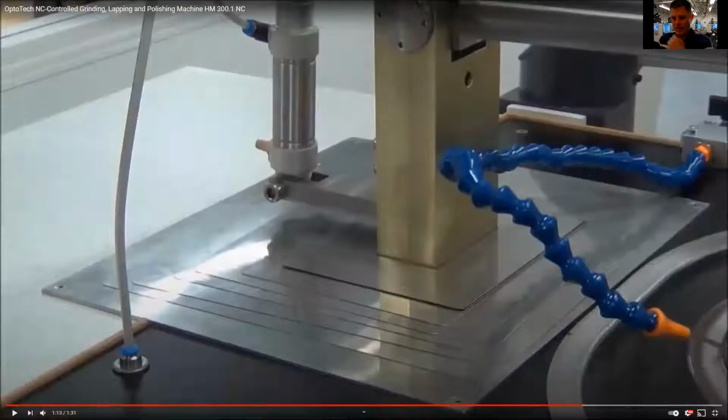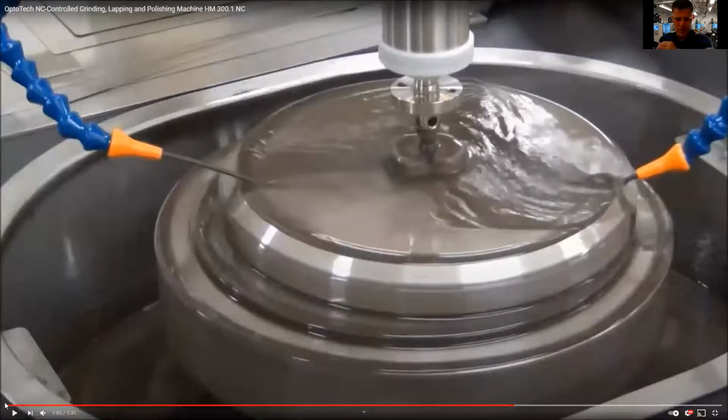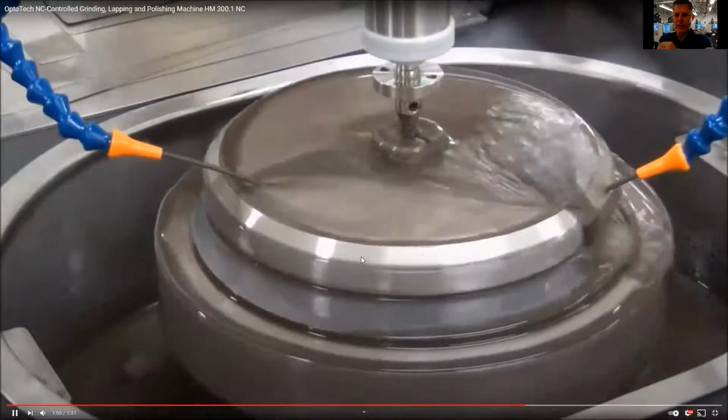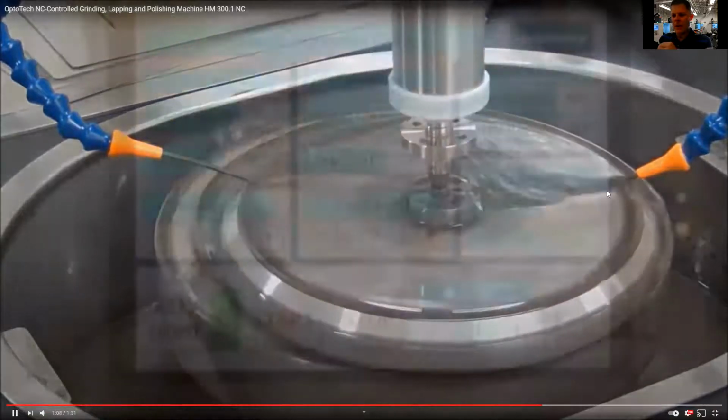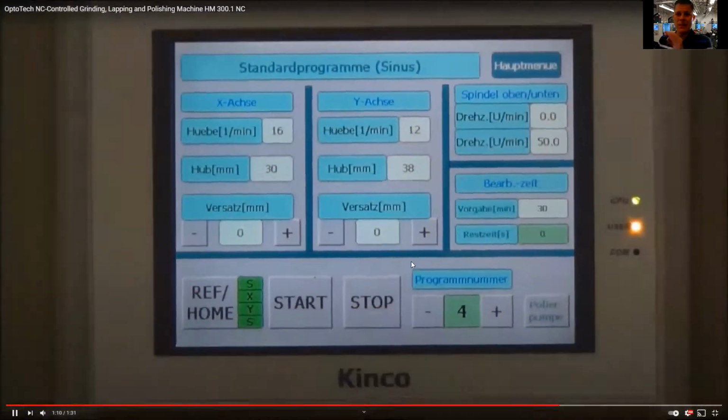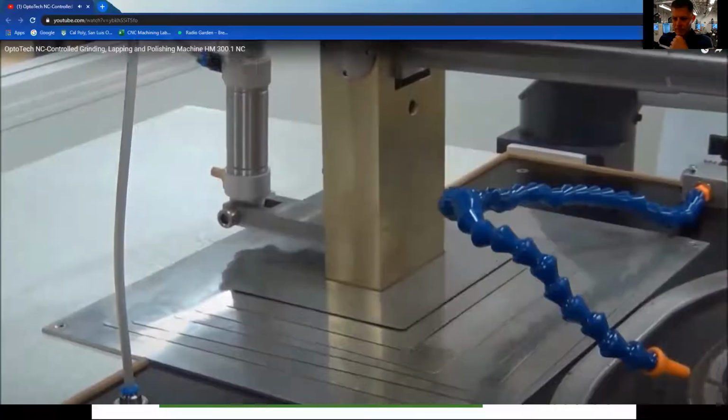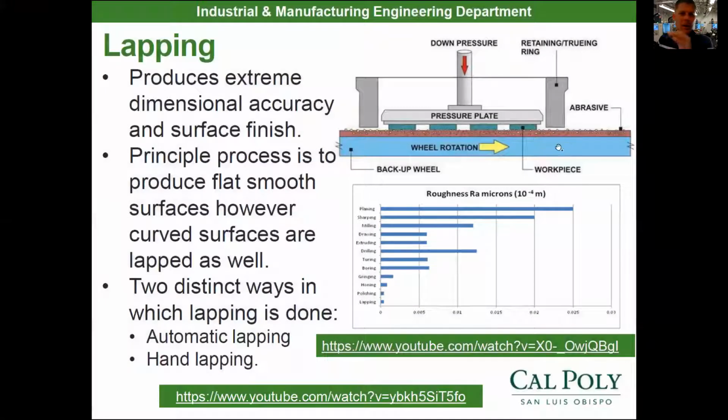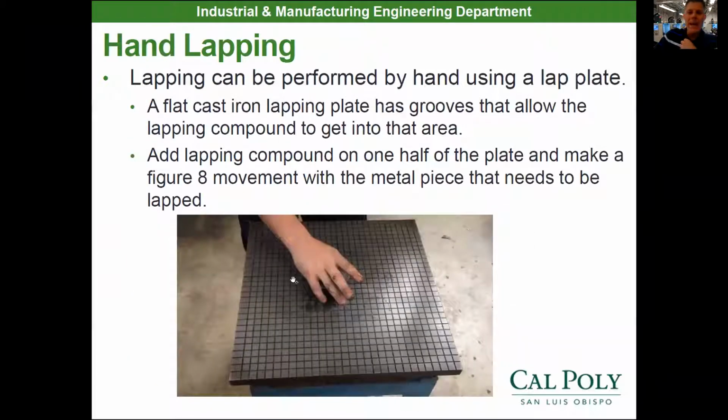but whoops, let me just press play here. Blurry here, and then you have the felt disc rubbing itself on top of that glass surface, polishing it. If you've ever had to repolish your car headlights because they got foggy, it's almost like doing that. You're using an abrasive grit to kind of just take off that top polished surface and polish back those headlights shiny again. So hand lapping now is usually performed on what we call a lapping plate.